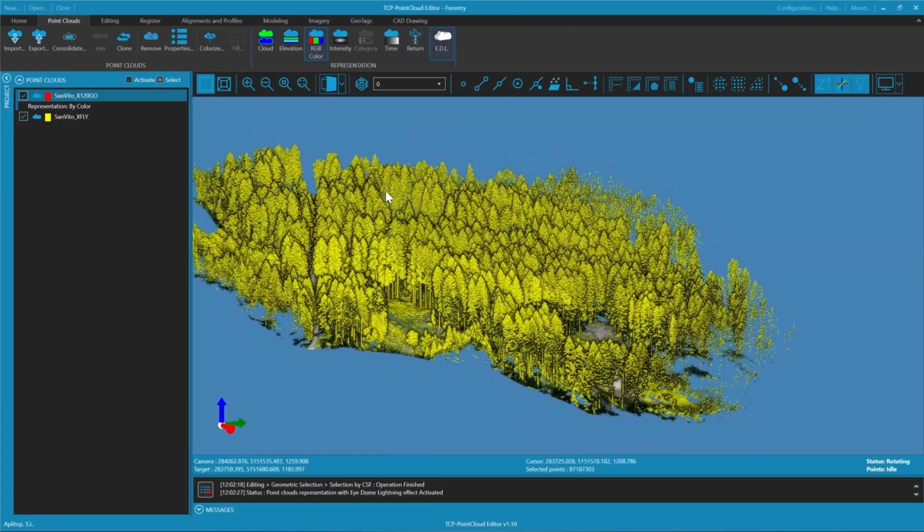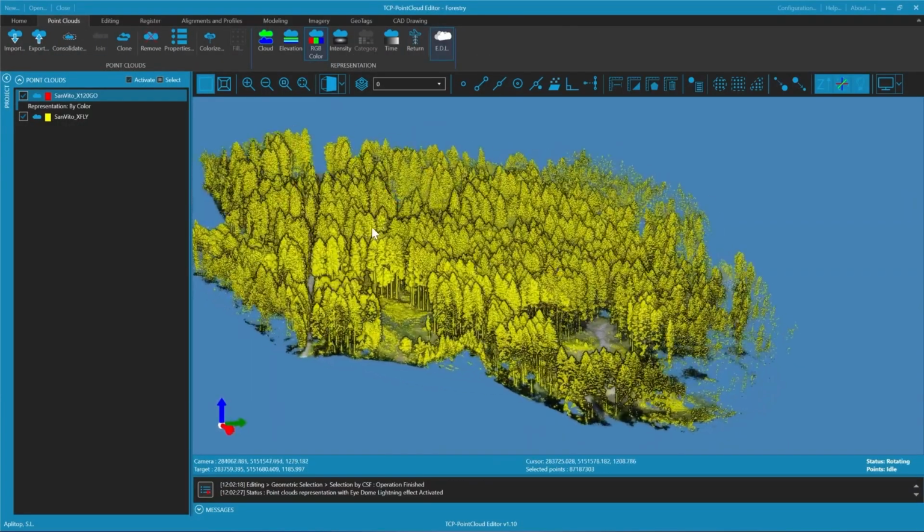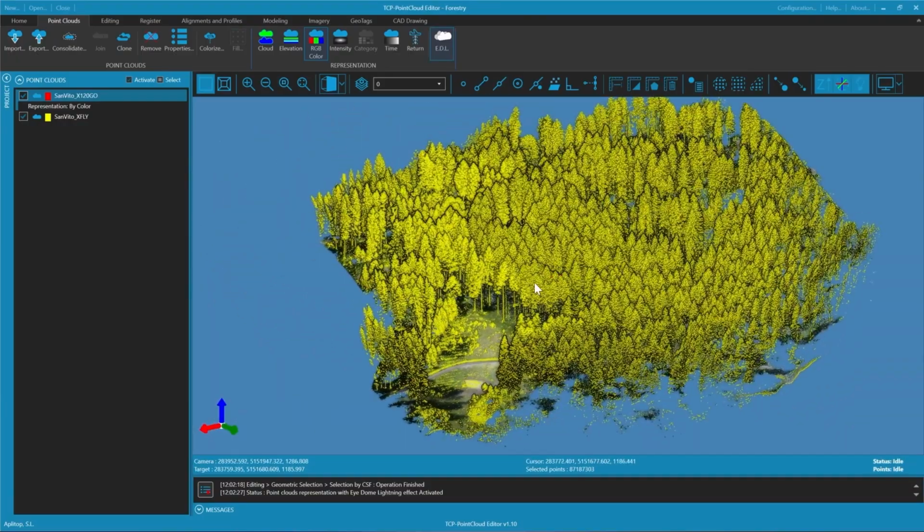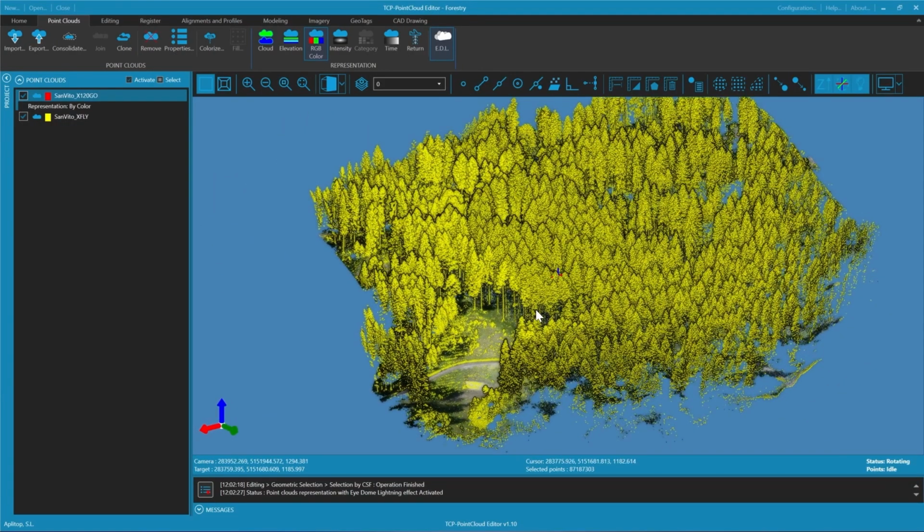So it's very weak against low noise points, and also at the borders, as you're going to see, because we don't have so much density and we miss the ground points. That's where we can have more issues, but we'll fix it later. So we run the filter at a resolution of 0.2 meters and let it work to find the ground.